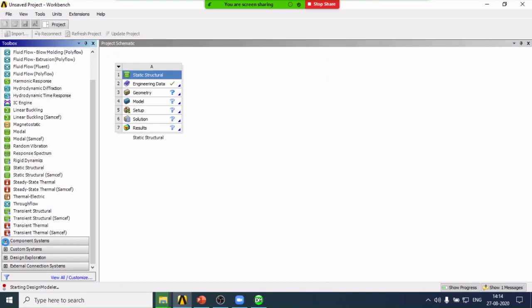So here you can look at the design model, where you can create your model. It's simple: I click onto this XY plane, right click, say look at the face, and then I go into the sketching. I'll start sketching with a simple rectangle. This is one rectangle I created. I need to give a thickness for it. Then let it be complete.